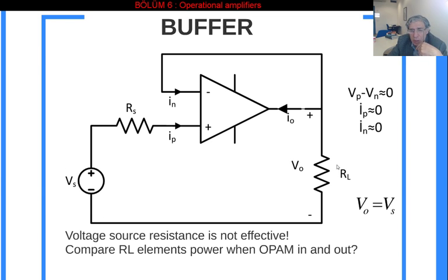So this is going to be the load of my circuit. So I have replaced the given circuit with the Thevenin equivalent circuit and put an R value here. That means RL is the load resistor. So the current passing through this resistor is going to be Vs over Rs plus RL. That's the current.